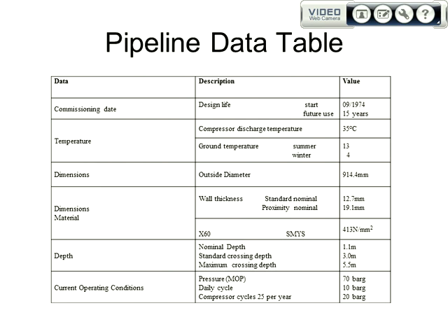The proximity pipe, that's the thick pipe, which will be present under road crossings or wherever there's any pinch points, population density infringements along the pipeline. Is it sleeves? No, it's proximity pipe, so it's thick pipe. TD1 at the moment doesn't advise using sleeves to protect the pipeline.